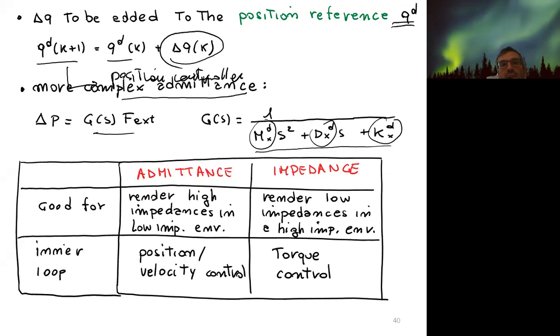While for high deviation, you have the problem that the Jacobian is not approximating the small displacement anymore, and the big displacement means that you need to move the end effector a lot with the position controller to give way to the force.